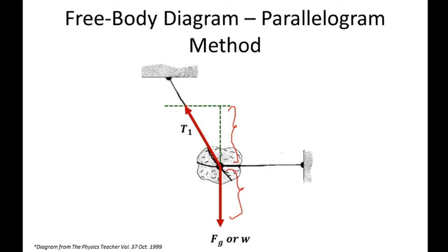Looking at the proportions, you would see that tension 1 is greater compared to the force of gravity. Meaning, the string is pulling the rock more than its weight. And then how do we draw tension 2? You draw a line parallel to tension 1 and you put it here. So this point right here is the end point of your tension 2. That is now of correct proportion.